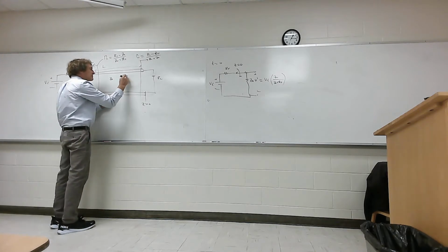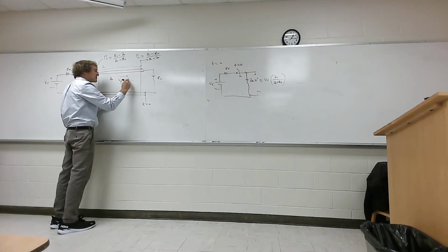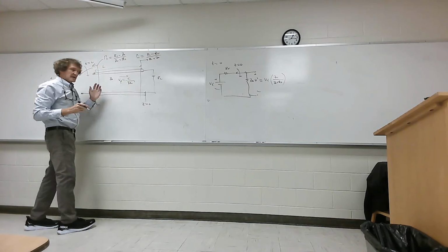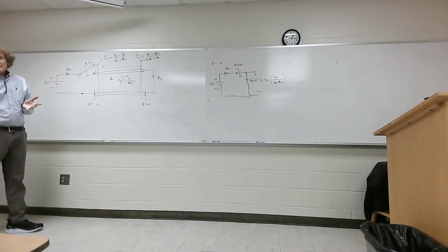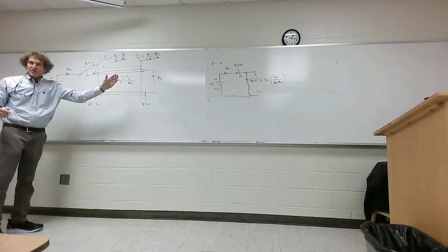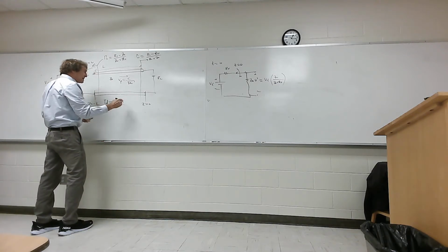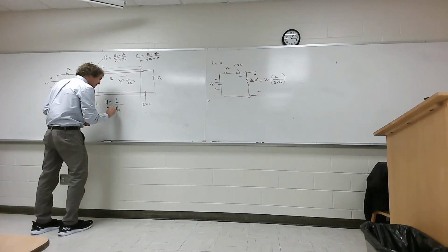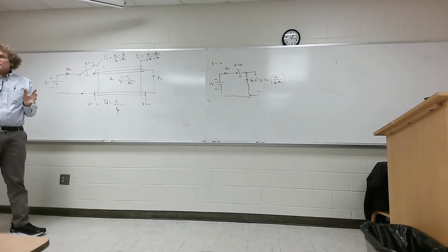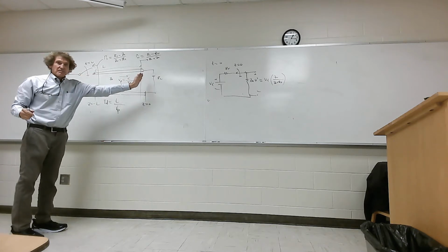There's also going to be a phase velocity on here, which will be c over the square root of epsilon relative of that transmission line. And the reason I need that is because I need to find the delay time from here to here. It's called just the delay time, and that's equal to the length of the line divided by V phase. Now, most of this should make perfect sense, how I got that, right? Distance is velocity times time. I need the time delay for the wave to go from here to here.